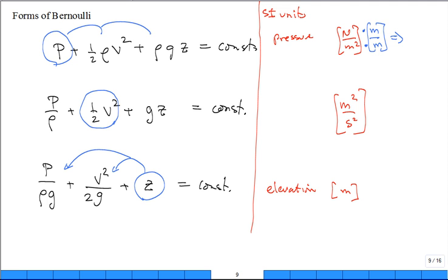And so what I have is a joule per meter cubed. Okay, what is meter cubed? Volume. Pressure, you can interpret. I know that every term in that form of the Bernoulli equation is pressure, but you can interpret that as energy per unit volume. True?